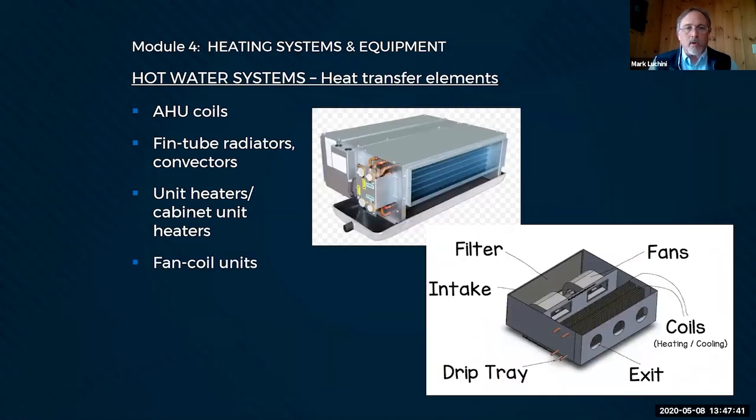We also use a lot of fan coil units in our business. What's the difference between a cabinet heater and a fan coil unit? A fan coil unit is designed to heat and cool. Typically, you'll have a hot water coil and a chilled water coil in there. In two-pipe systems that use the same piping for heating and cooling, and just switch the water in it from chilled to hot, you might end up with a single coil, but it would be a cooling coil that you run hot water through, basically. Up at UMass Lowell, we had a 2-pipe system and 4-pipe fan coils. Go figure.